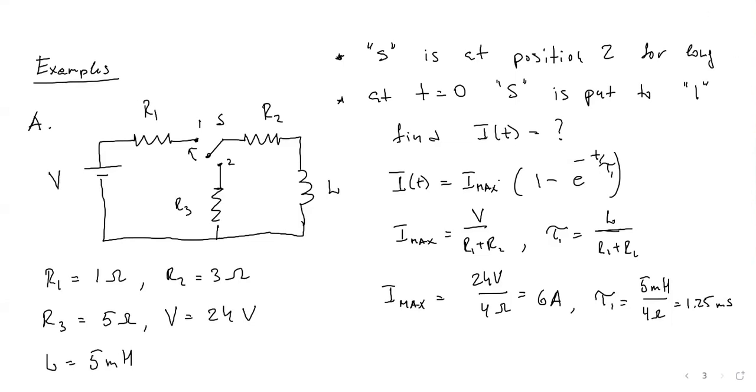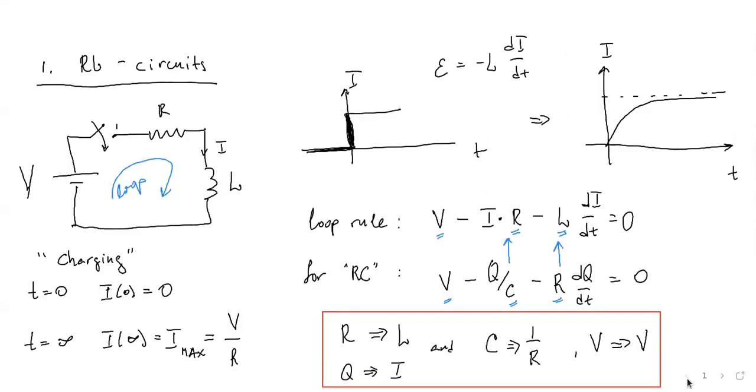Let's go back to the picture I drew before here. The difference between very sharp change and a slow change. So inductance will play a significant role in this. If my inductance is small, then the time constant is small, so it's going to be a very short process. If inductance is 0, it will be very sharp. When you just close the switch, if there is no inductance, the current will jump up in almost no time.